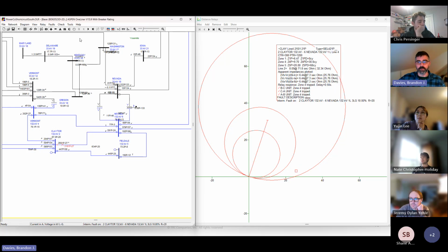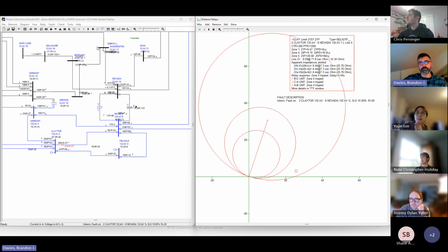It's less of a concern maybe for a three-phase fault like what we've shown here, because it's really hard to just apply a balanced resistance to three energized transmission conductors. Generally, it's more of a concern for ground faults, but you can apply the same kind of approach to any kind of fault here, and do that same thing.